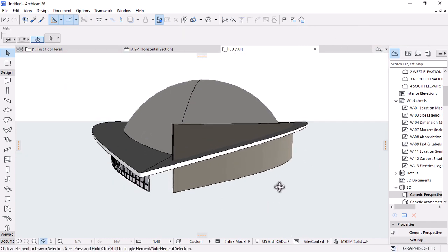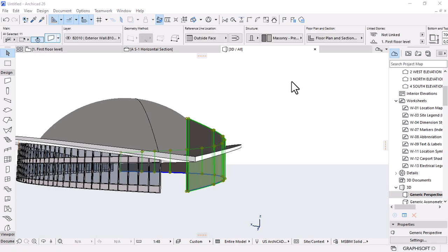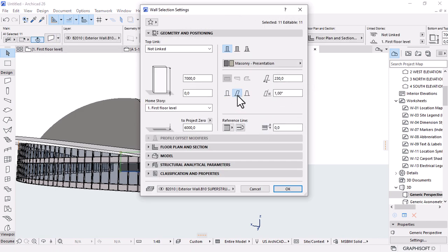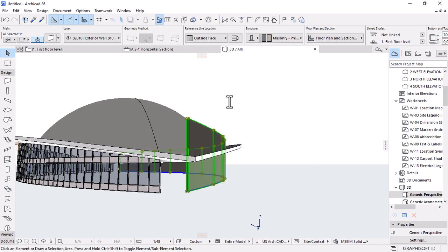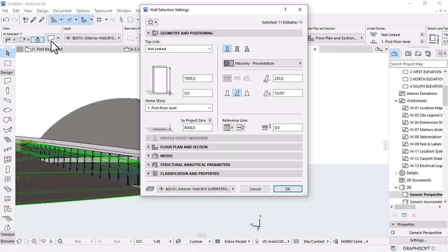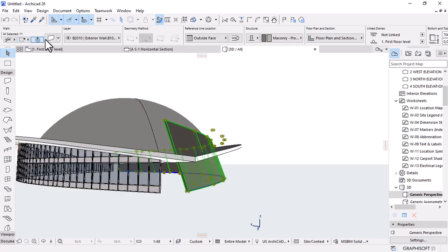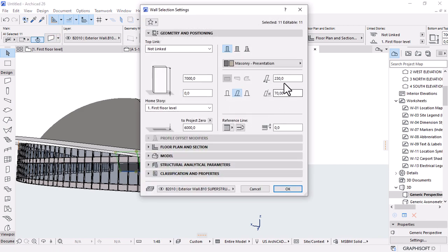and then what I was trying to achieve is, if you open the settings of the wall, you can make this slant maybe by 10 degrees or something. Or 10 is too much, eh? Let's say 30, maybe 70. I want it to slant outward. Let's say -70 there.